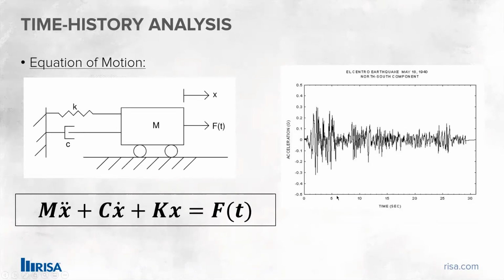For solving each step, we will plug in the forces of that particular step into this equation and get the response of this whole system for that step. And then the result of this step will be used as the initial condition for the next step. So we're going to solve it step by step, and then we can get the total response for this system, for this particular seismic load.